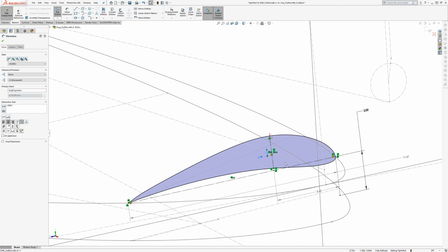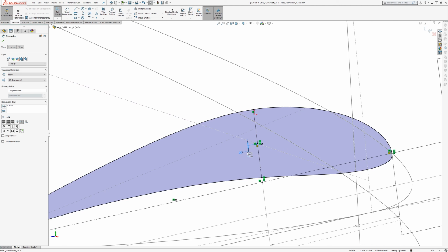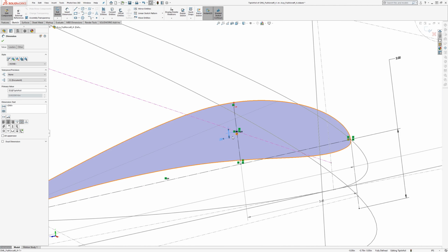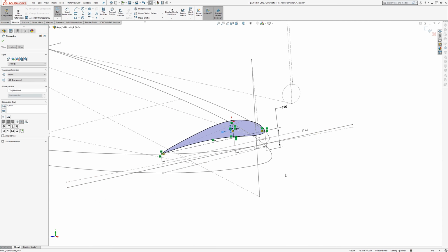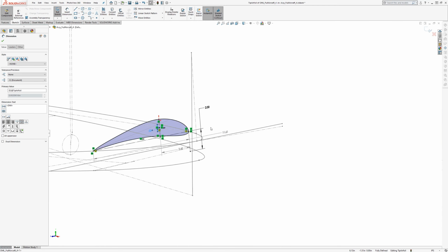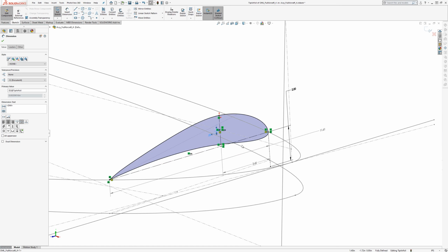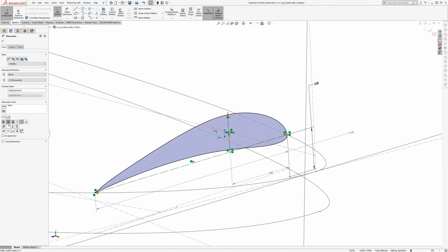The tip airfoil is not actually forced to be on that line, but it ends up being, I adjusted the tip dimension at the tip airfoil sketch there, that 0.77, so that it aimed it in the end to pass right through that point.